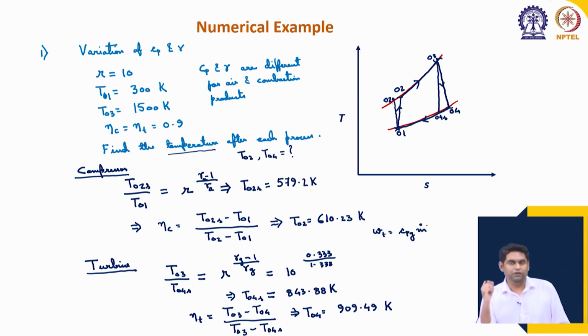So, if we are doing the problem in terms of per unit mass flow rate of air, this will be m dot g by m dot a, because that is the ratio of the mass flow rates. So, per unit mass flow rate of air in the turbine we have larger mass flow rate, multiplied by (T03 minus T04).